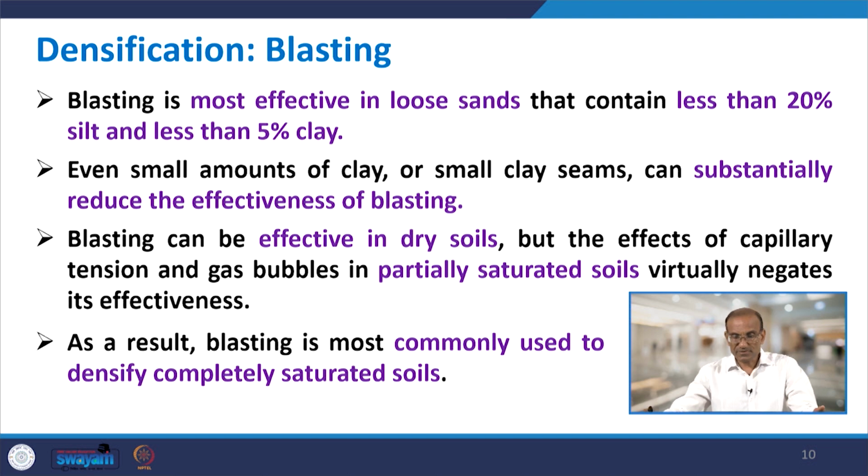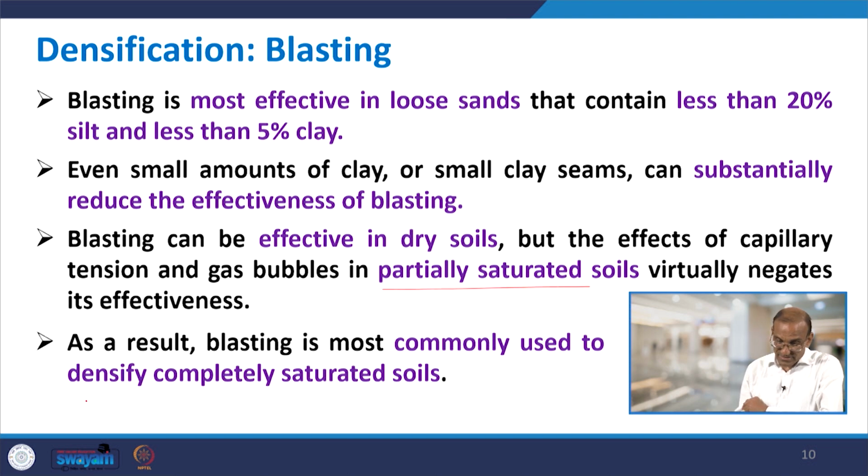So, the effectiveness of the blasting technique will decrease if you have partially saturated soil. If you have dry soil, good, but if you have partially saturated soil, then there is a problem. However, if you have completely saturated soil, then it is fine.